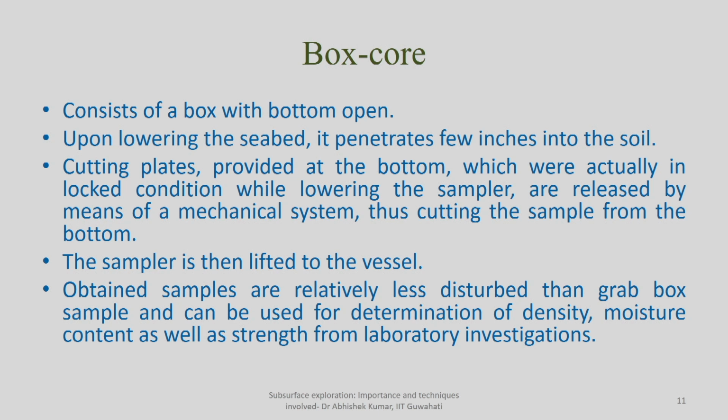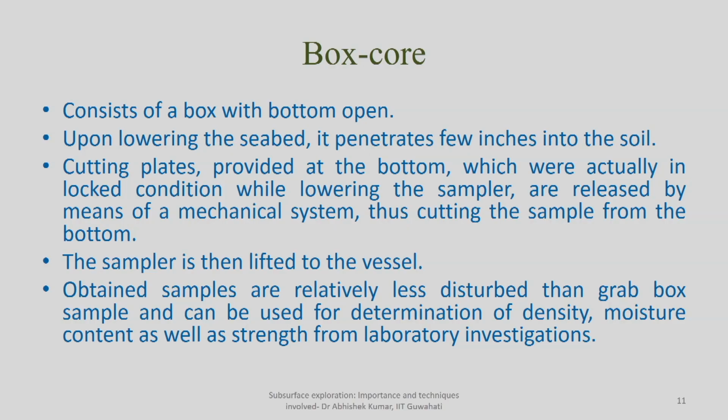The cutting plates provided at the bottom, which were in locked position, are released by a mechanical system while lowering, and as a result they cut the material collected at the bottom and contain the sample collected up to that particular depth, thus cutting the sample from the bottom.